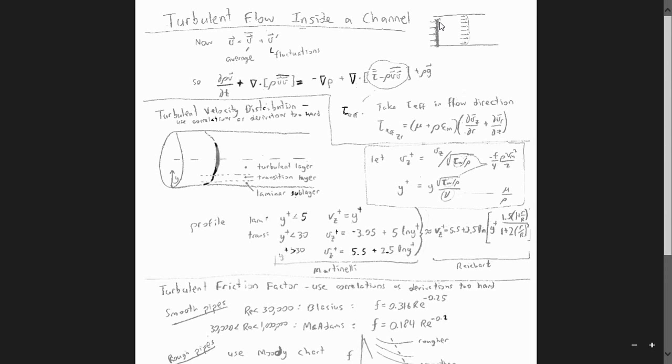in a horizontal configuration. So what happens is when the flow enters a tube, you will see a flat velocity distribution at the beginning, but then due to friction with the wall, just as in laminar flow, the fluid can't slide over the wall, so the friction at the wall causes the velocity to be zero at the very edge where it contacts the wall.